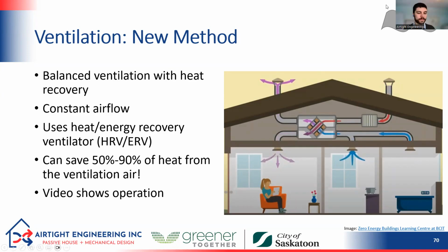Okay. So there's a quick description of what a heat recovery ventilator does. And I will just note the difference between a heat recovery ventilator, or an HRV, and an ERV, which is an energy recovery ventilator. So an ERV is able to recover both heat and humidity. So this is actually quite helpful in Saskatchewan. So lots of times we would recommend ERVs to our clients because it's dry, it's cold in the winter, and so if we can recover some of that humidity from the air, it's actually going to make it less dry in our houses in the winter.